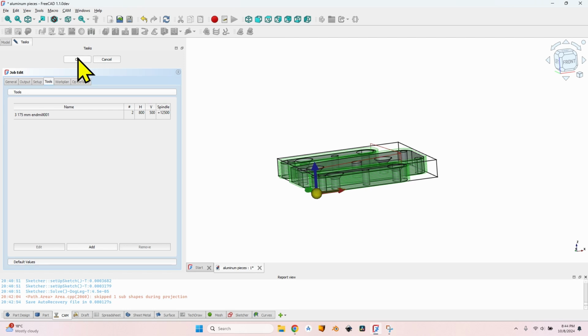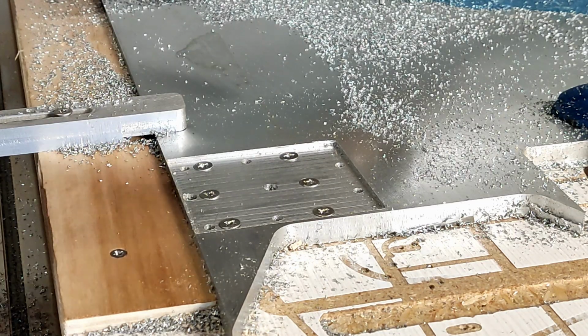So these are the settings for this type of material. For aluminum, I believe it's a 5000 series aluminum, and of course my machine with this certain tool bit. You can take them as a guide, but you must know that there's no identical setup, so learning how to set everything up is a matter of experimentation, a matter of trial and error, and over time you will know exactly what setting to use when milling certain types of material with certain types of tool bits on a specific machine. So let's add some little more WD-40,